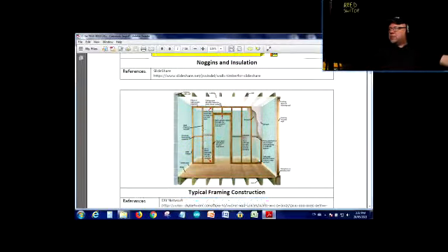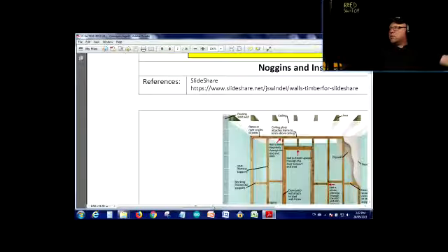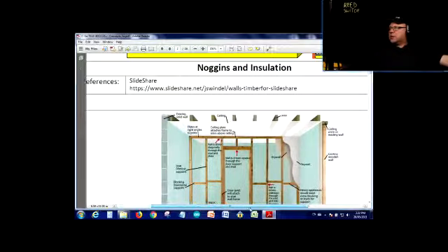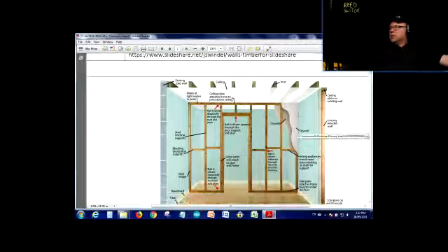Now, here's a typical one. Zoom in a little bit more. Can we do this here? There we go. Now, on top, there would be joists as well. So sometimes when you can run the wire in the ceiling, if you're lucky, and if you just want to go from the front to the rear of that wall, and if you run into a setting where your joists go with the way you're running the wire, then yeah, bonus, you can run it.